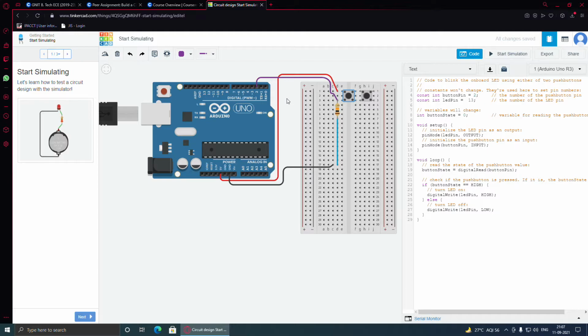So in that case, what we do is we use resistors of different values, say in some cases 10 kilo ohm, 5 kilo ohm, 7.5 kilo ohm. So why do we use the resistor? We connect the resistor in series with that component, the component which has a low current rating and a low internal resistance.